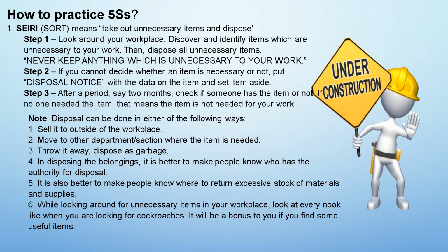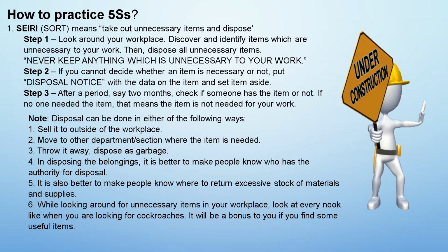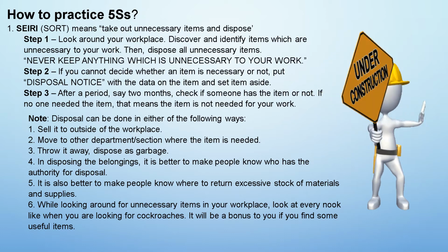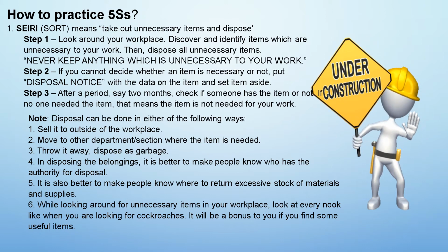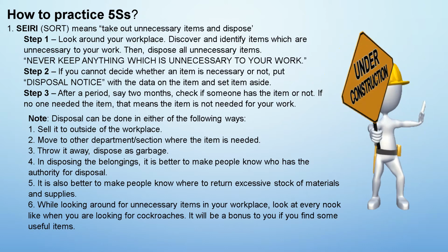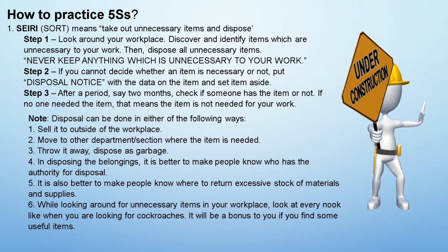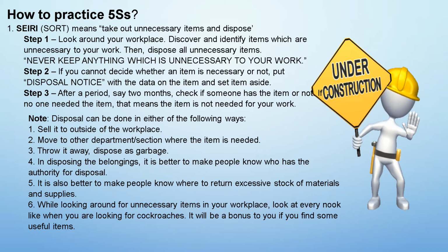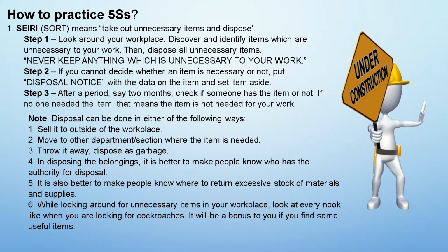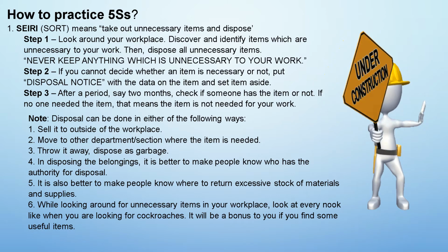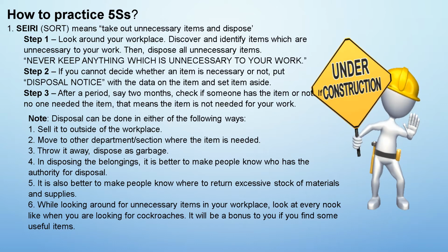Okay, how to practice the 5S. First, the Seiri, or sort, means take out unnecessary items and dispose of them. Step 1. You should look around your workplace, discover and identify items which are unnecessary to your work, then dispose of all unnecessary items. Never keep anything which is unnecessary to your work.